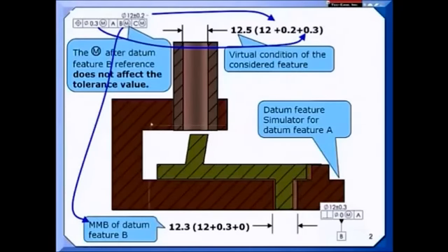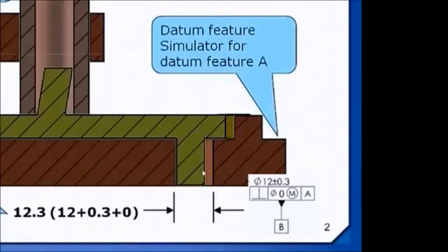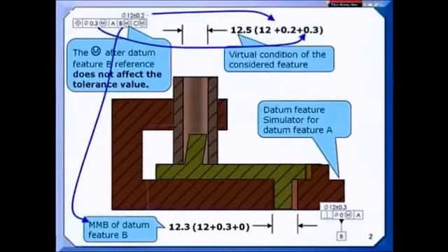If you believe that this M gives you additional positional tolerance, let's say that this boss comes in at 12 or down at 11.7. There's an extra 0.6 shift that you could have total here. If you treat that, though, as a bonus on this considered feature, not only are you saying it can move out of position more, but you're also saying that it could tip more, because orientation is included within position, if you remember the GD&T hierarchy. In this case, that orientation is perpendicularity.